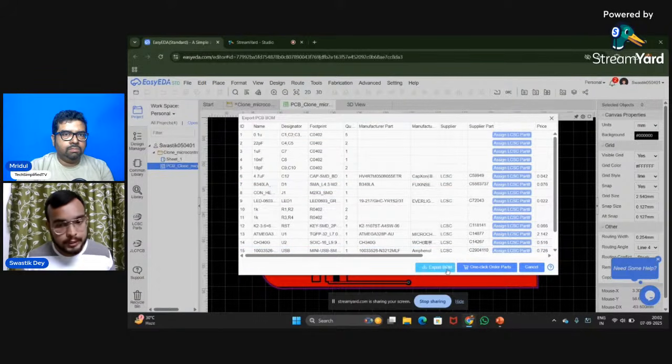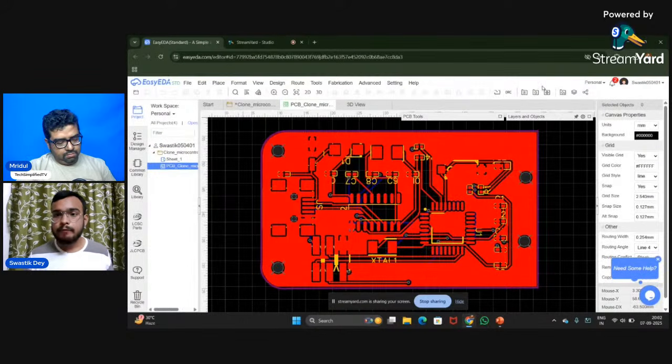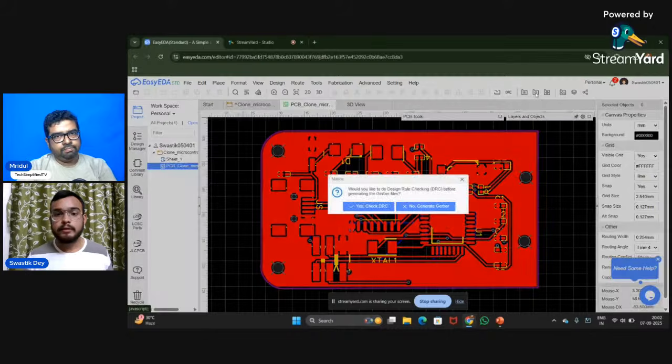By clicking on this export BOM, we can generate our bill of materials file, and of course we can always contact a PCB manufacturer and provide them with this file. And for the Gerber files, we need to click over here.